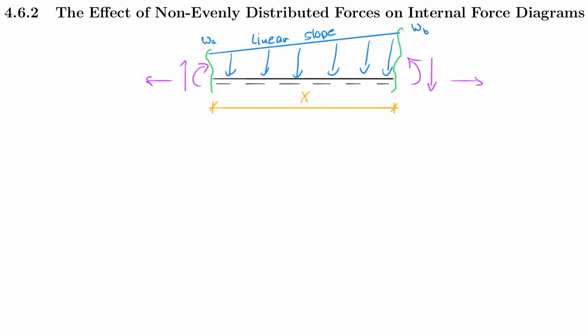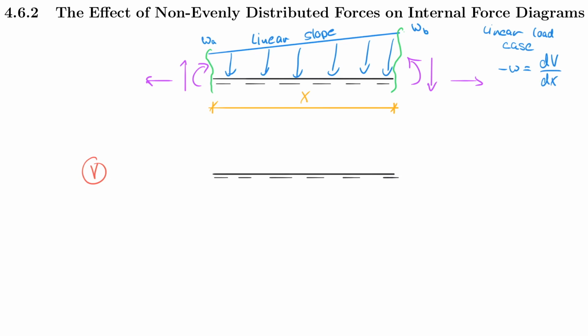But my goal now is to think about what happens if I want to apply that load case to my shear force diagram. And to draw the shear force diagram, I start with my rigid body and I start calling this the shear force. And the thing that I remember, right, is that here I now have a linear load case. And I also remember that minus w is equal to dV/dx. And thanks to that formula, I can now extrapolate my knowledge from the previous section and understand that I can also take the load case and integrate to arrive at the shear force function.